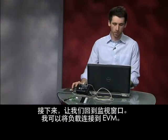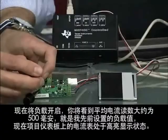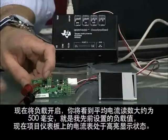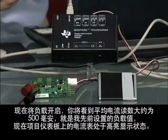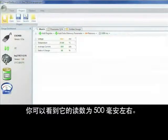So now let's go back to the watch window. I can connect a load to my EVM, turn my load on, and you'll see that now the average current is reporting around 500 milliamps, which is what I have set my load to, and the ammeter on the project dashboard is now highlighted, and you can see that it's also reporting about 500 milliamps.